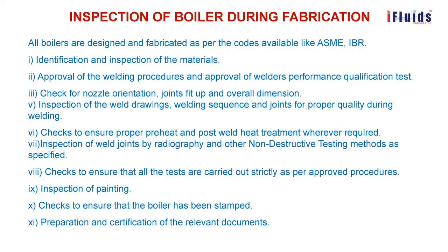So to identify this location, this will be matched with the drawings and with the angles provided there, so that it will not mismatch during erection. So everything should be in its place and it should be appropriate to confirm with the availability of the boiler erection. So check for nozzle orientation. This orientation is a very important point.